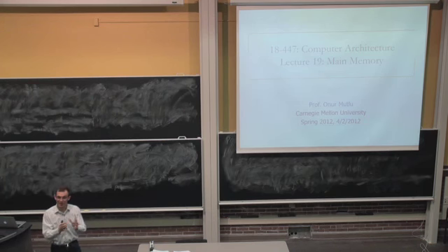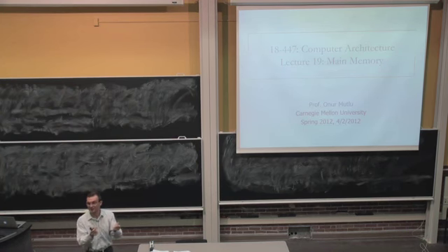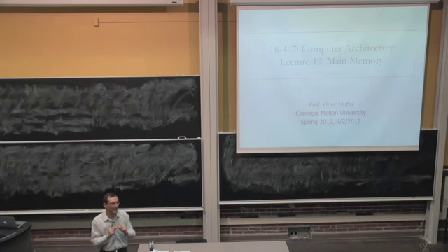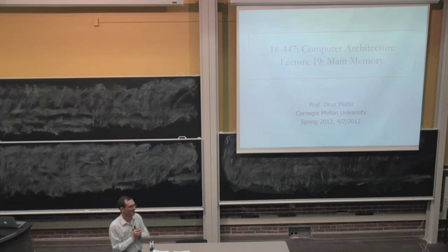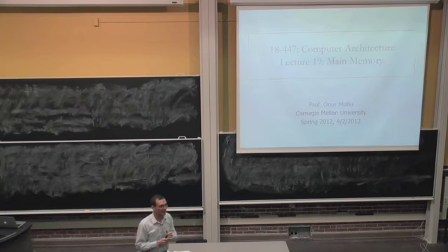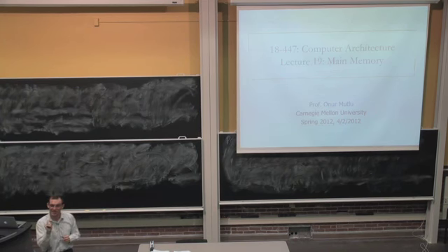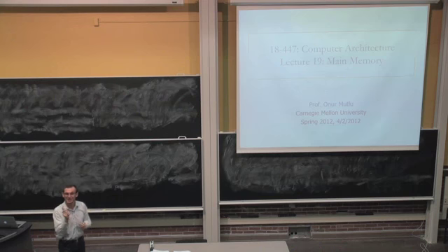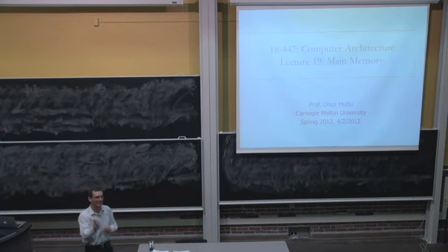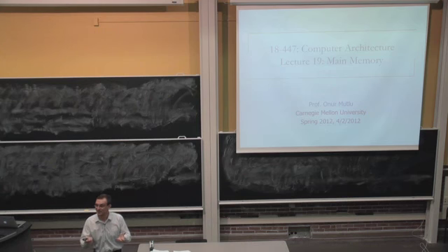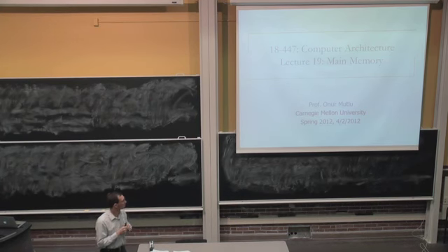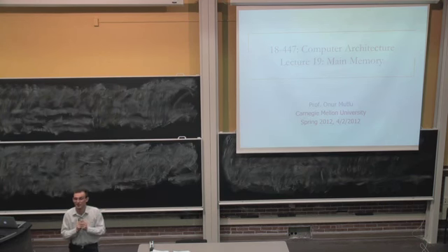As you make the size of this thing, bank, smaller, it becomes faster, right? And as you buffer stuff within each hierarchy, you exploit locality. So those fundamental principles will never change, regardless of the technology. Technology just changes, if you will, what is the latency to access a cell? What is the latency to sense it? What is the latency to read it out or write to it? And these are very much dependent on technology.